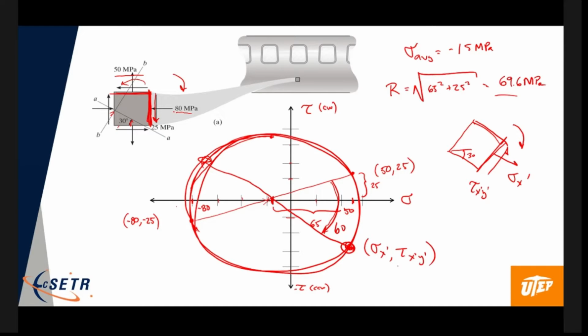You can figure out the direction. It's a negative value, so it's going to make it counterclockwise, so it's going to go that way. This value here would be on the top face, so it has a negative compressive stress. This would be sigma y prime, and likewise the shear stress going that way. And that's what you get. Those could all be computed graphically.